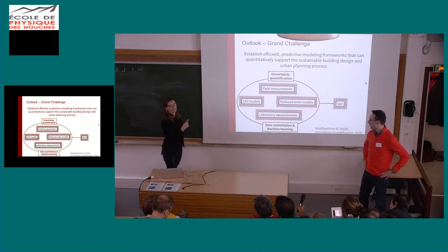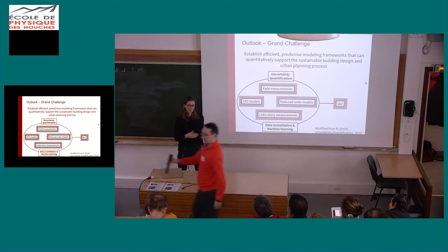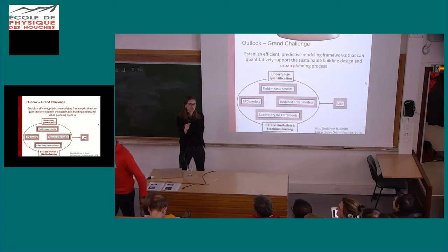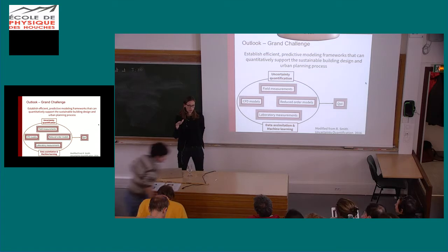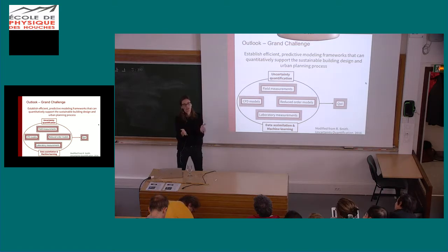So we can run this uncertainty quantification with any turbulence model. We have done it. We did this study for a wavy wall where we used both a realizable k-epsilon and SST k-omega model. The bounds that you get are obviously different, right? Because you start from a different point in the triangle when you do the perturbation. But in both cases, it gives you bounds. And usually they bound the DNS prediction, and they definitely bound the initial RANS prediction as well. So the bounding behavior is consistent. Does that make sense?